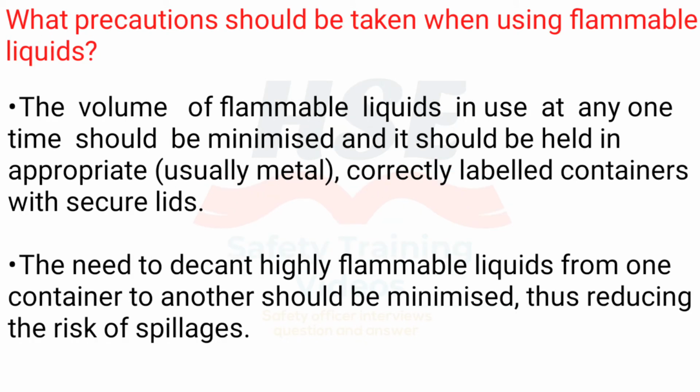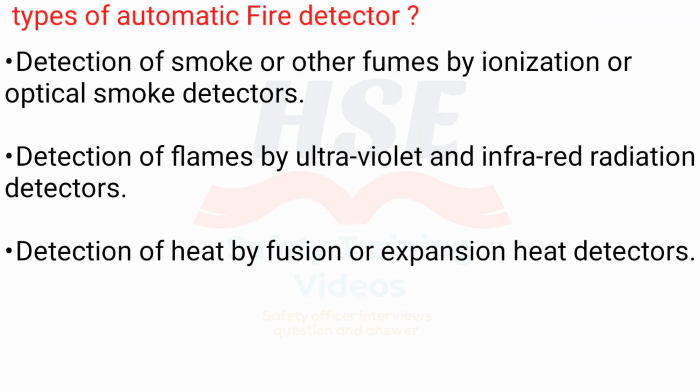What precautions should be taken when using flammable liquids? The volume of flammable liquids in use at any one time should be minimized and it should be held in appropriate, usually metal, correctly labeled containers with secure lids. The need to decant highly flammable liquids from one container to another should be minimized, thus reducing the risk of spillages.